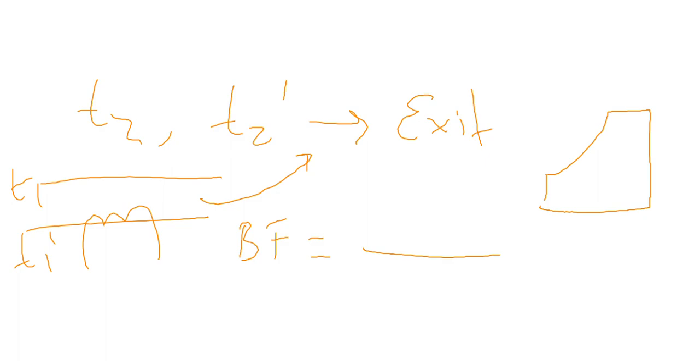So this was your 1, this is S, and this is 2. If you look at the psychrometric chart, the bypass factor is T2 minus Ts, which is the temperature drop, and in the absence of bypass, the drop would have been T1 minus Ts, right? So this is known as the bypass factor.